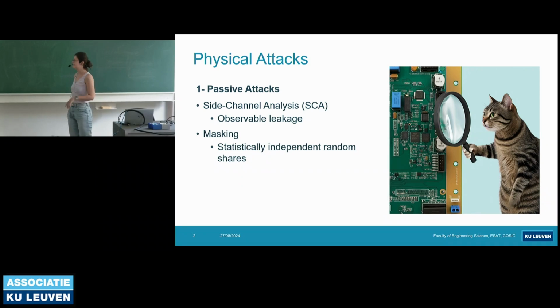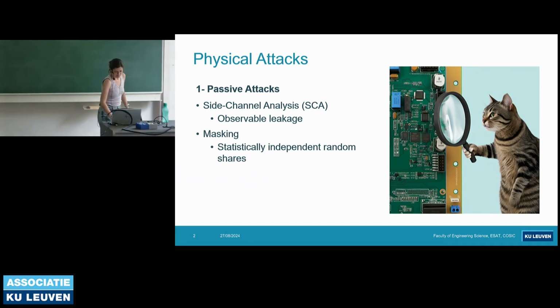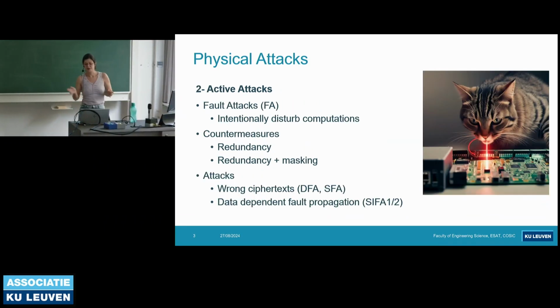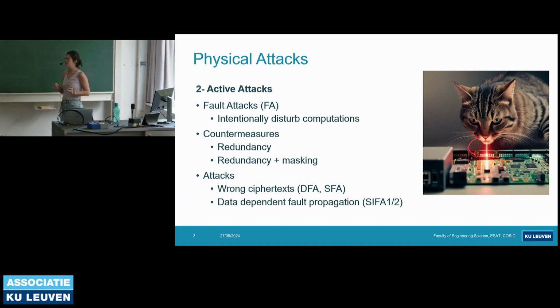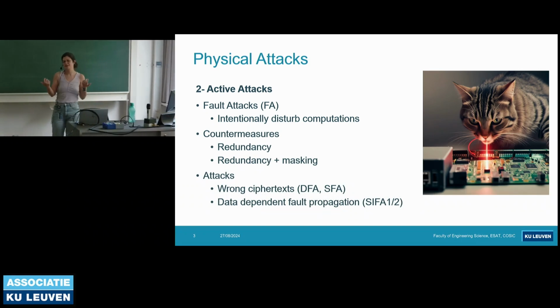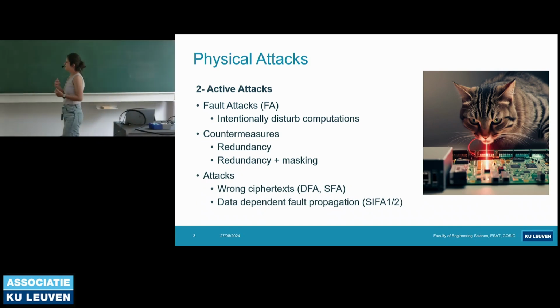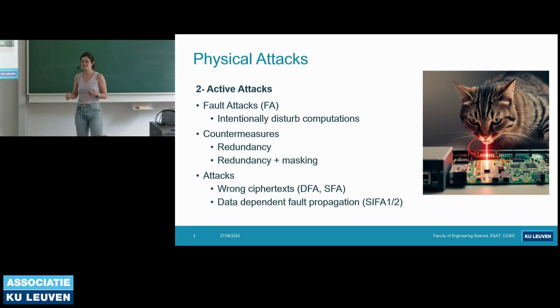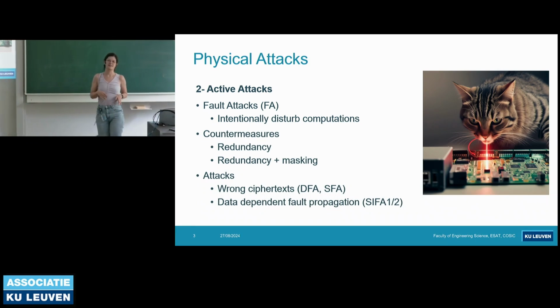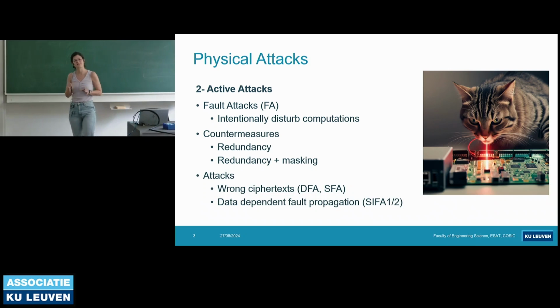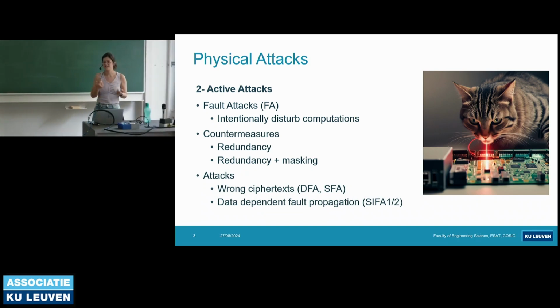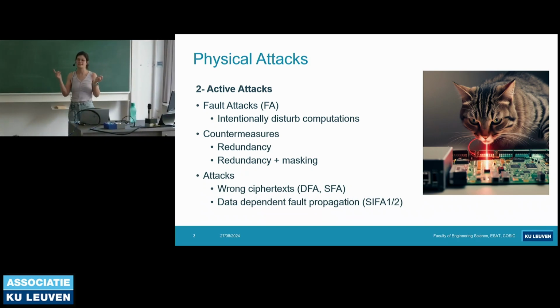And the second category of physical attacks is the active kind of attacks. And these are the well-known fault attacks. In fault attacks, unlike side channel analysis, the adversary is intentionally disrupting the computations by injecting faults into the computations using some physical fault injection mechanisms, such as clock or voltage glitching, EM waves, or laser.